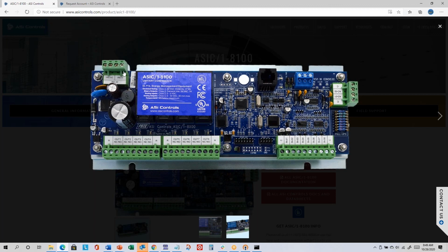We do give you 2 terminals here. Usually you don't need to use the second set here because these are relays with independent returns, so there's no triac wiring concerns in terms of needing to take hot down to a field device. And then this controller also will try to ground itself through its metal base. So if the mounting surface is grounded, then you don't need to do anything special with the common terminal. If for some reason the mounting surface is not grounded, then you could use one of the common terminals to ground the controller.